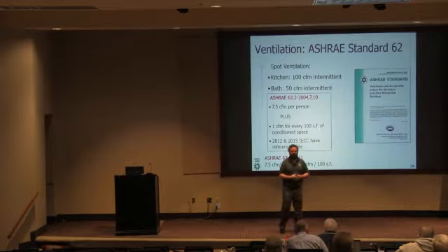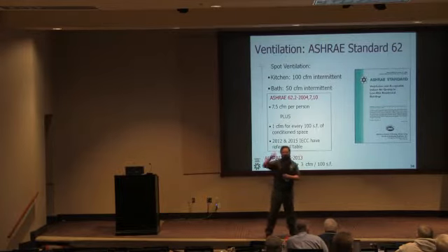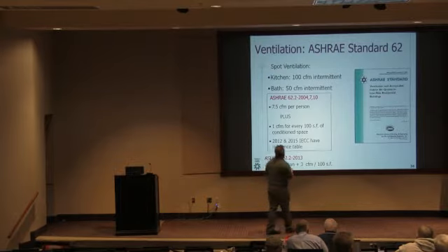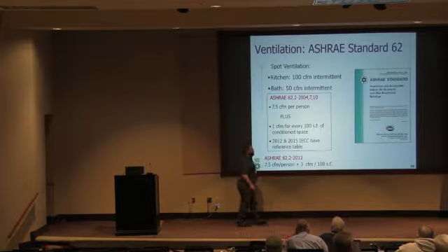So these are spaces in homes that do need intermittent negative pressure ventilation, and at a minimum, per the ASHRAE 62 standard, kitchens need 100 CFM, baths need 50. Of course, kitchens get way more than this typically.